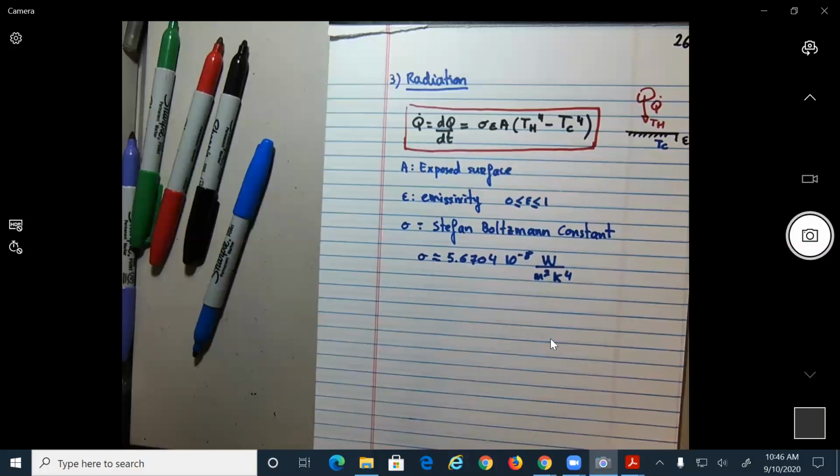Again, I'm not going to give you too much detail, but this equation is correct for the applications you do. If you go into more detail, do you think the absorptivity needs to be equal to the emissivity? For example, how a body absorbs the heat needs to be equal to how the body gives the heat back to the medium. That is what happens in most materials, but it's not what happens all the time, no? So really, this value here might be a different value for each one of these temperatures, which changes the equation slightly. But for this class, this is good enough.